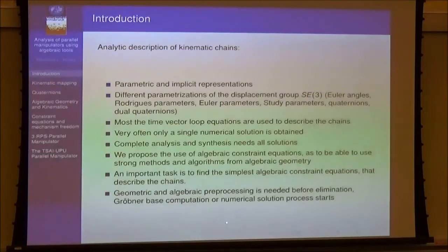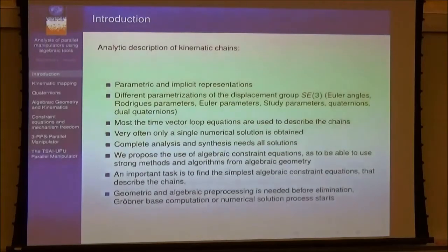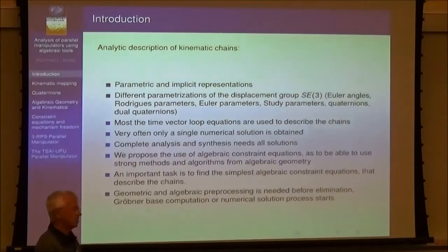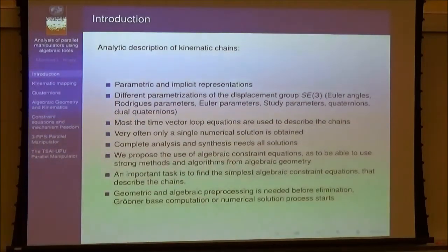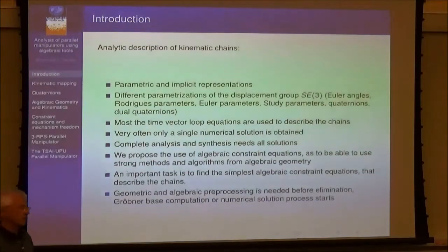It's also recommendable to do this pre-processing before you go into something like what is called the Gröbner basis and numerical solution processes. Even when you are only interested in finding numerical solutions, it makes sense to find out first what are the simplest equations describing your kinematic problem.